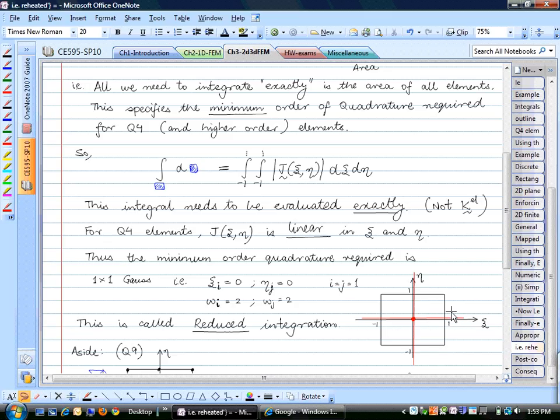But there are also a posteriori measures. What that means is after you are done calculating, you can use certain error measures, and we'll talk about that also. You can use certain error measures to characterize that in this part of the mesh, my error is greater, so I need to refine this part of my mesh. So in general, yes, there are lots of procedures where you can check what is the error in your solution. Obviously, it will not be exact because it is just an error estimate, but that will allow you to get closer and closer to the solution you want.